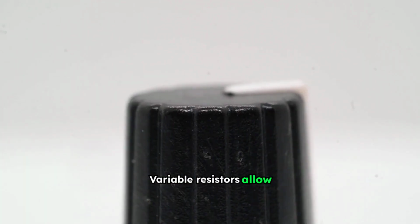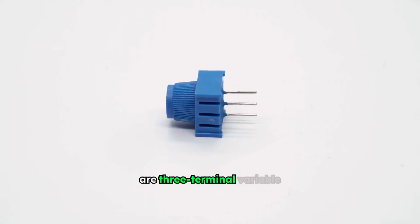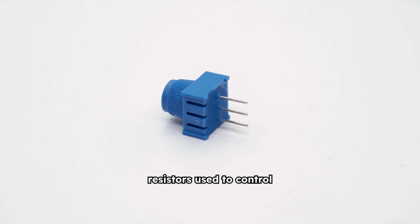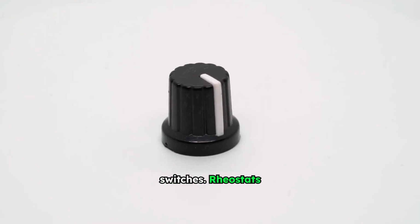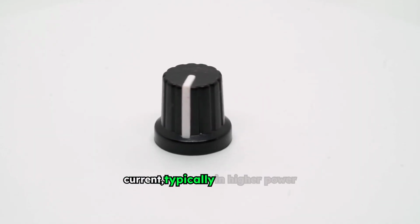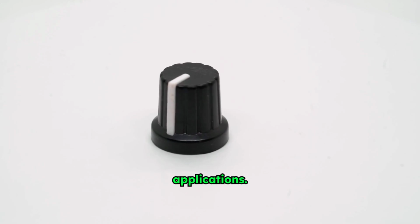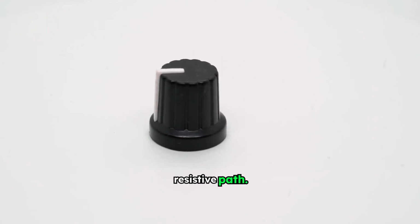Variable resistors allow their resistance to be adjusted. Potentiometers are three-terminal variable resistors used to control voltage, often found in volume controls or dimmer switches. Rheostats are two-terminal variable resistors used to control current, typically in higher power applications. Adjusting these components changes the effective length of the resistive path.